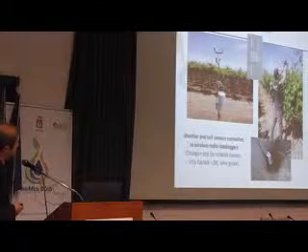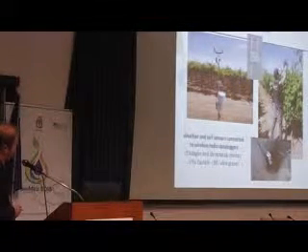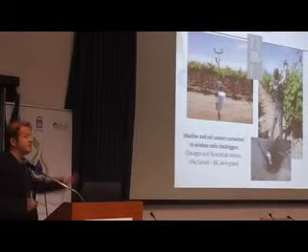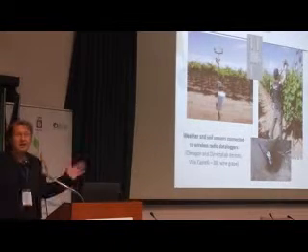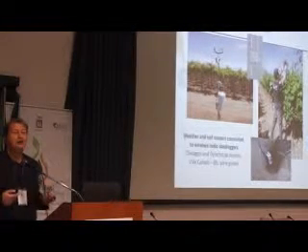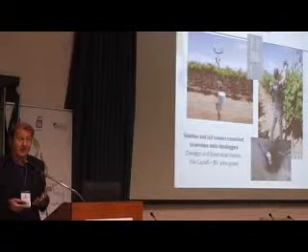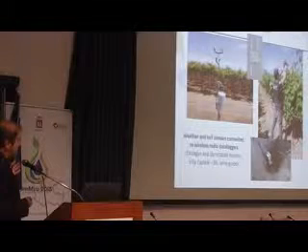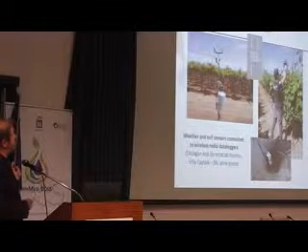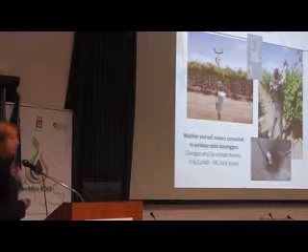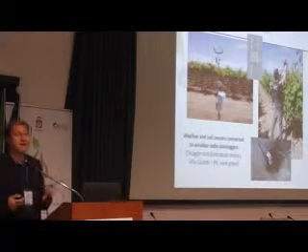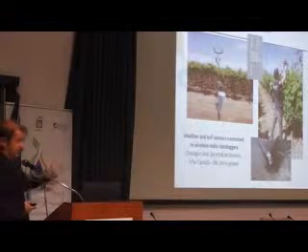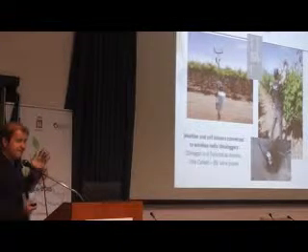In brief, examples of installation of a weather station. You see it is installed in the field, but those conditions are not standard conditions, so what we are getting are not perfect data. We are going to use temperature and humidity, which we can say could be adequate. Precipitation could be adequate, but usually we don't have enough fetch to accept wind speed values as good ones in this estimation. So there are a lot of problems.